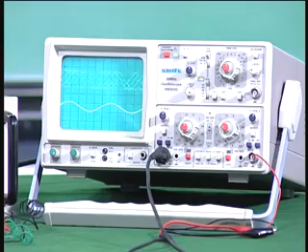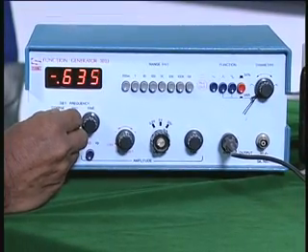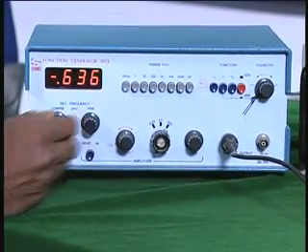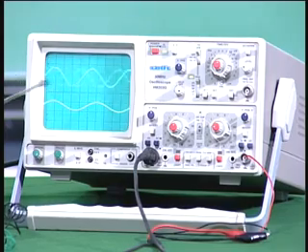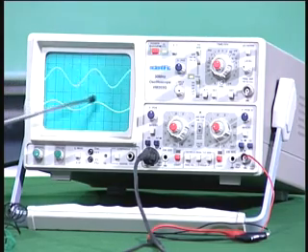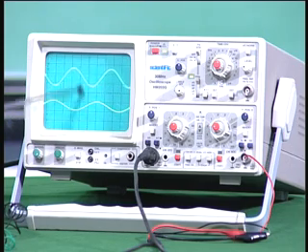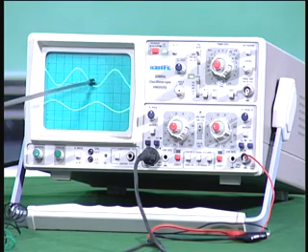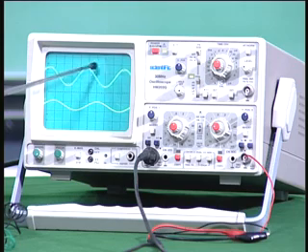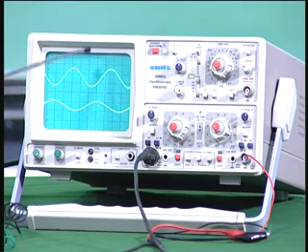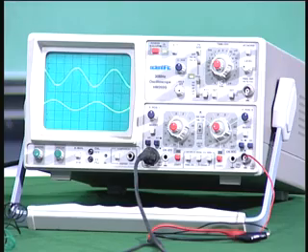I will show you. Now if I change the frequency in the oscilloscope, you can see the 2 signals. This steady one is due to the oscillator that we have constructed. This one is from the standard oscillator that I have used. Now what I am trying to do is superpose them and measure the frequency.